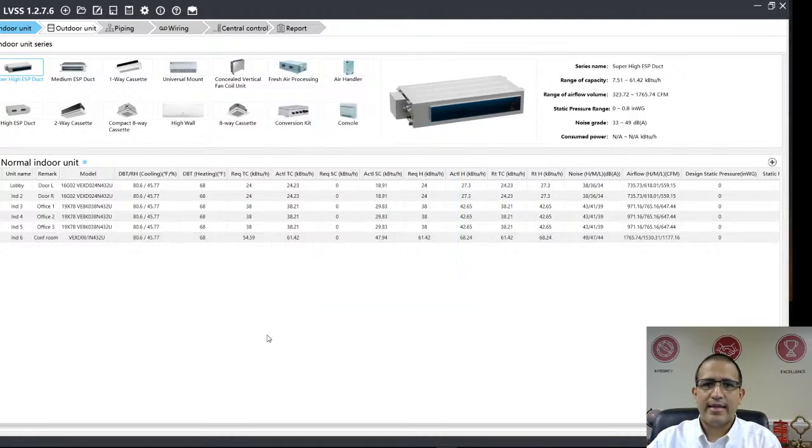And you start adding evaporators as you go, as you wish. So let's say your project has 50 evaporators. In most cases, what designers do is they go through the list of the 50 evaporators, which you can do by all means. In my experience, when I use the software, sometimes I get confused with so many on the list, so I start adding by system. So my system 1 only needs 1, 2, 3, 6. So I select 6, and then I go and select the other units. Once I'm done with that system, I save, and I go back and select system 2. That's the way I do it, but you can do it whichever way you want.